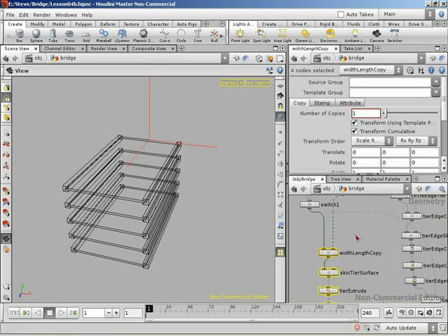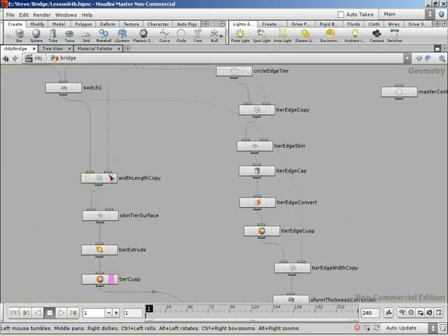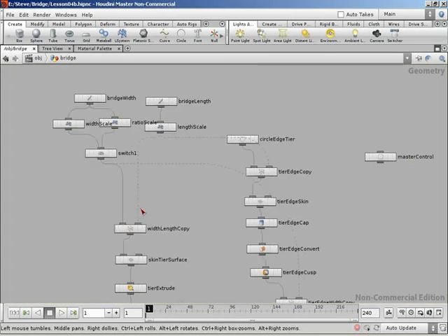There we go. Let's actually maximize this guy. We see what we're doing. This is where we're copying our length curve to our width curve to our length curve, and then we're skinning that surface. Just before here, if we have that toggle checked, I want to resample the curves so that we increase the number of points, so that there's going to be more points on them when they're copied, and that's going to result in more divisions in our skin and all our surface that's generated from that.